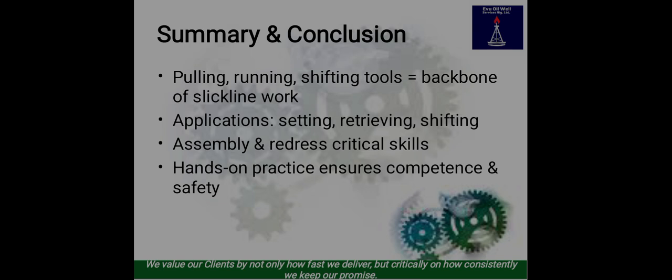And what is the root cause of all this drama that is costing the client money? Several small errors combine to create this failure. One: wrong tool selection, excessive jarring before confirming engagement, poor tool maintenance, no pre-job verification of sleeve type.